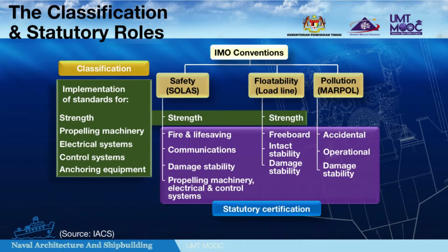These limits are given in the form of freeboard, which constitutes, besides external weather and watertight integrity, the main objective of the convention. In 1966, the Load Line Convention was adopted by IMO, and provisions were made to determine the freeboard of ships by subdivision and damage stability calculation.